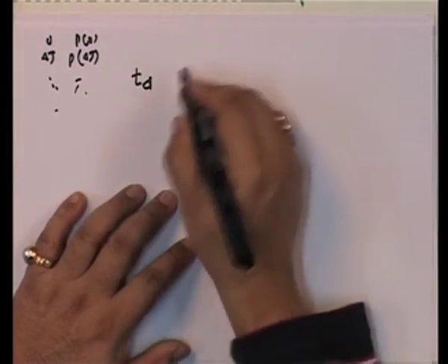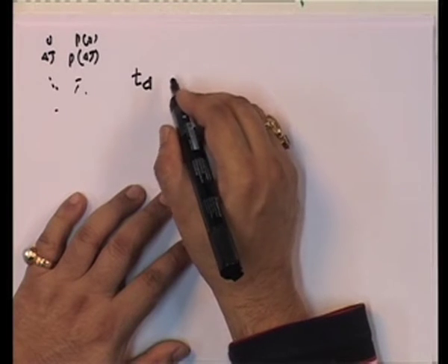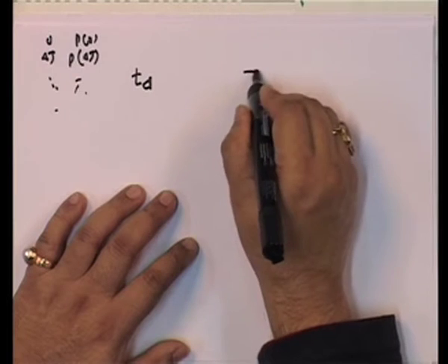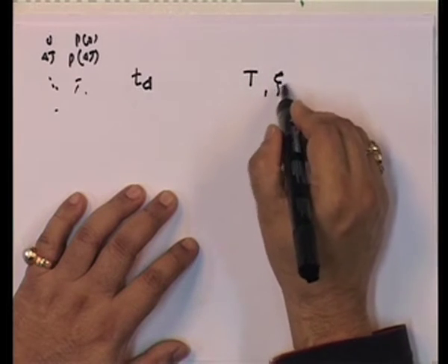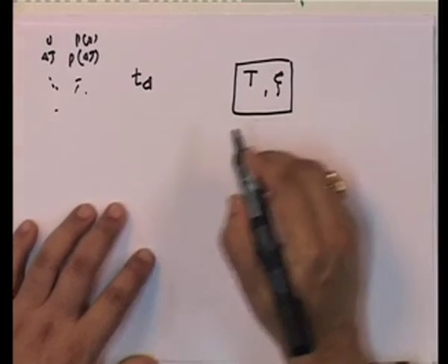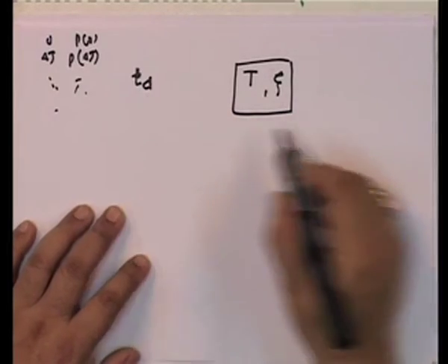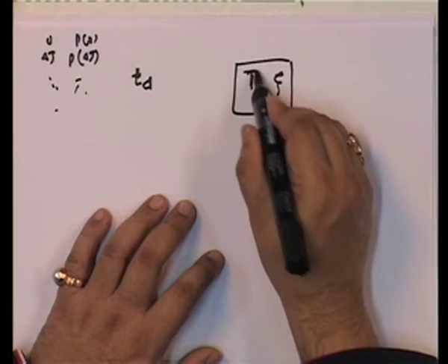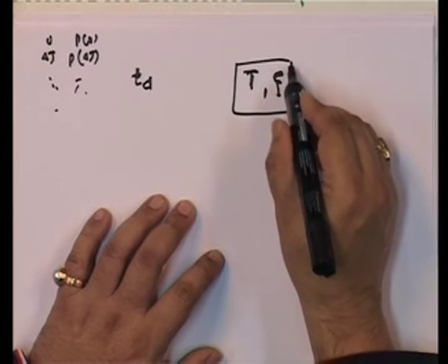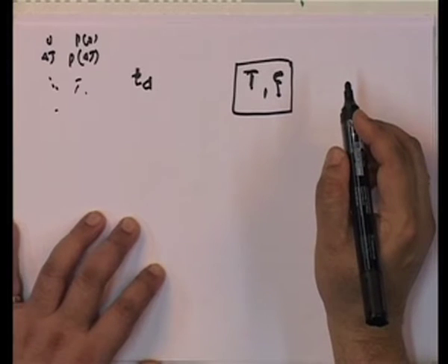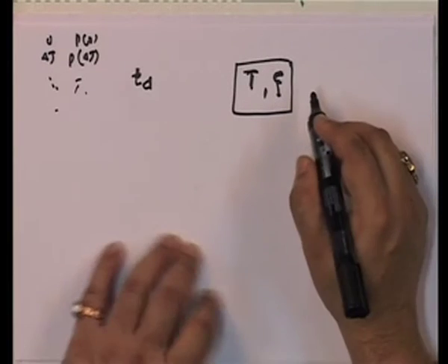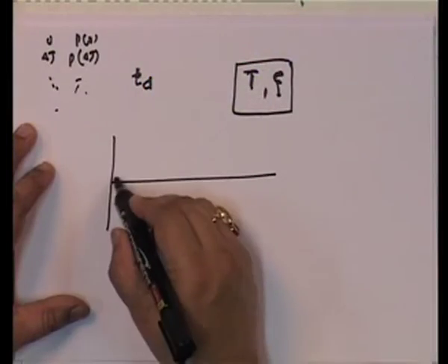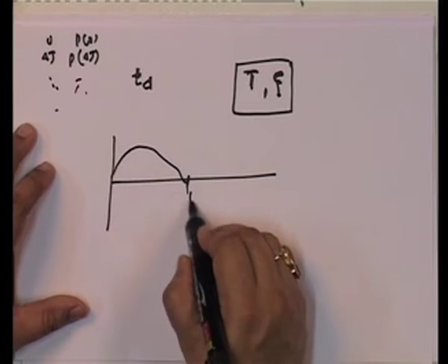Once I know time duration, look, I am going to be doing it for a structure. So, I know T and I know xi. I have a load with a fixed duration, and I have a structure where I know the T and xi. Once I know T and xi, I know that because I am going to make it a periodic load, I need a sufficient number of zeros. So, in other words, I am given this record up to T d.